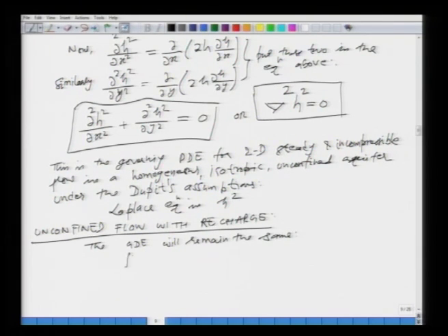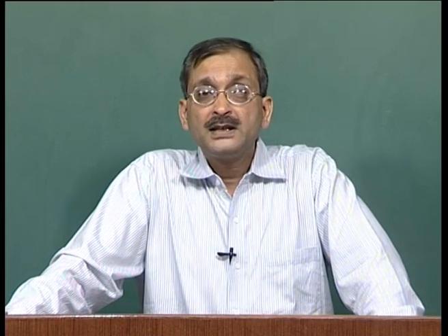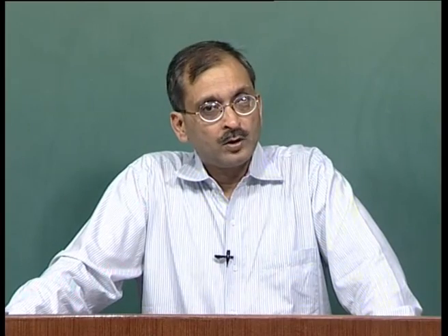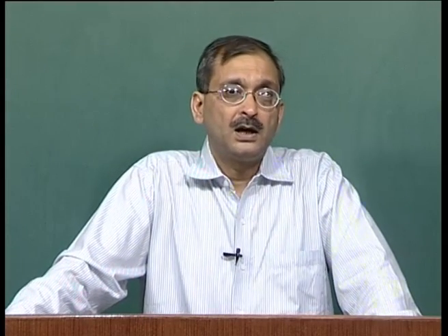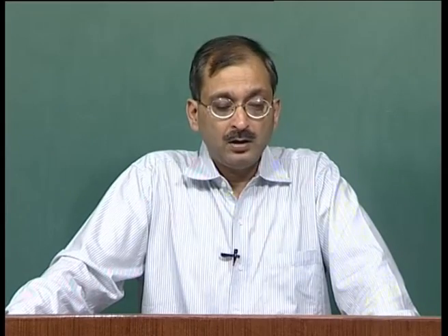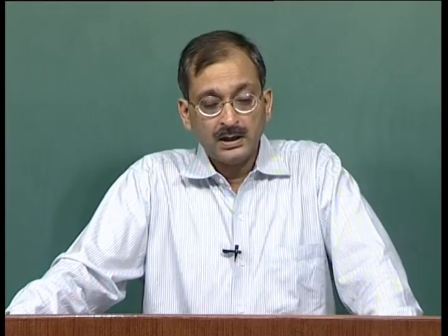It will be the equation we had written earlier from the Reynolds transport theorem. That is to say, the second component in the Reynolds transport theorem, the net outflux of the extensive property flowing across the control surfaces, is equal to 0. That is your continuity equation, and that remains the same.